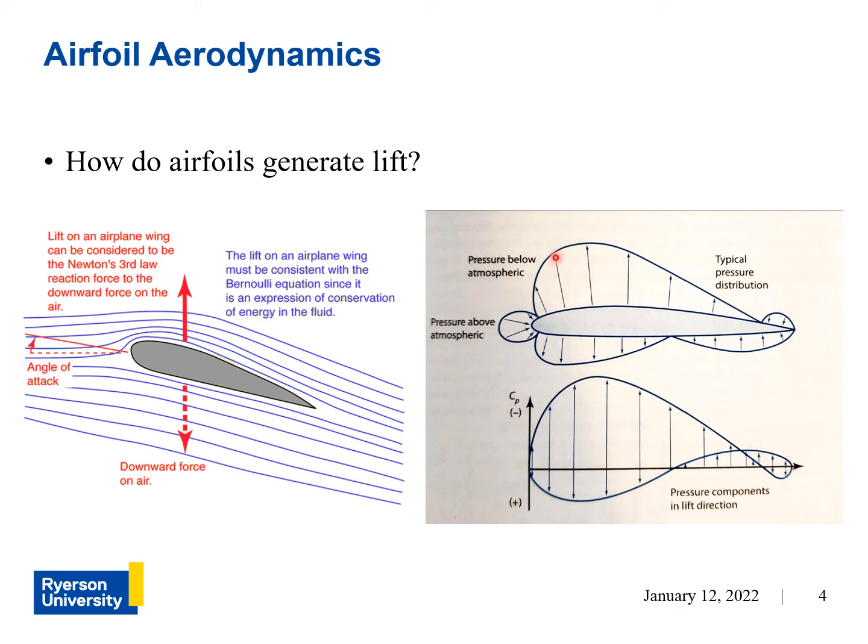And it also represents, in terms of vectors, lower than atmospheric pressure. So you can see here at the top surface, there's a large area where the air is below atmospheric pressure because of the way the air is traveling above the surface of the airfoil here.